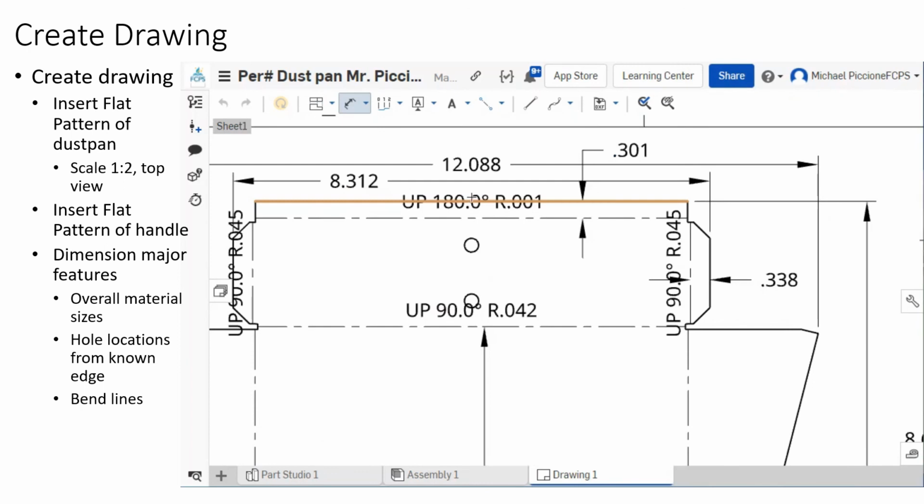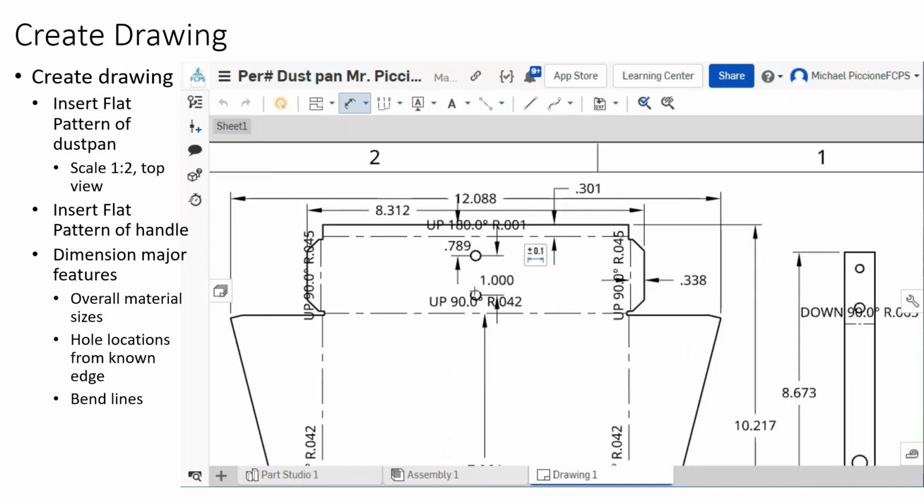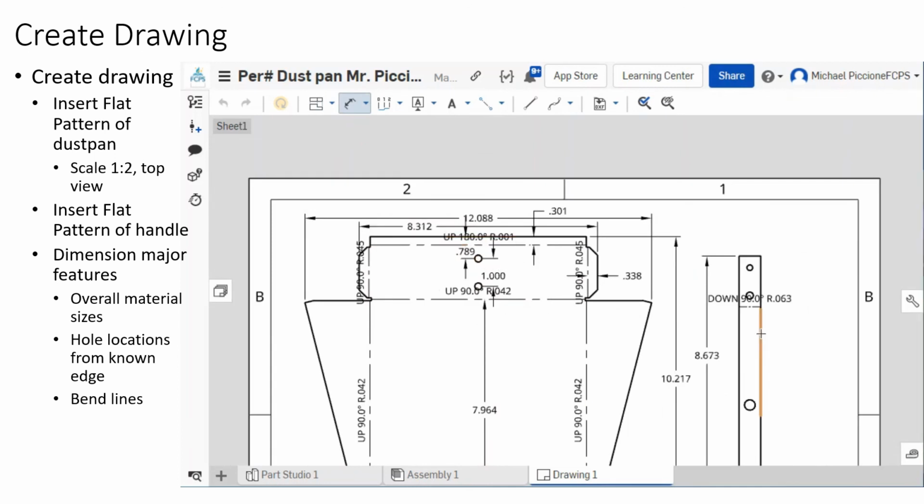One important feature I forgot is to lay out where the holes go, because we will actually use that information in real life. Another benefit of why it was really important to put the holes in the model is that this will allow us to lay out the flat pattern and cut the material, then drill the holes in real life before we start doing all the folding.